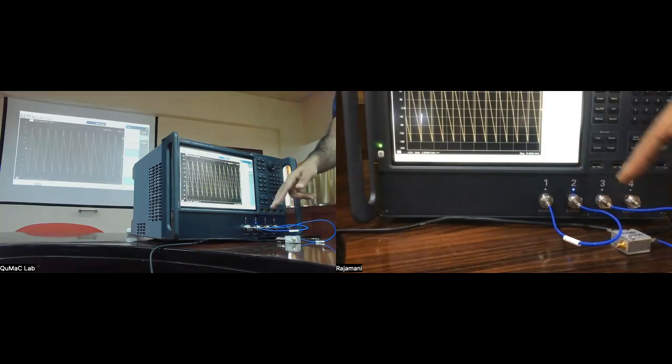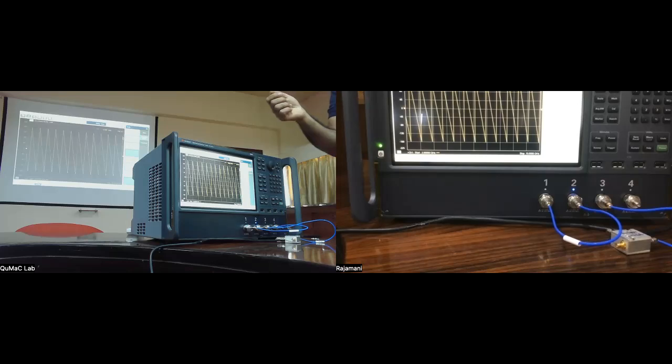This is a small cable, okay? In our experiments, these cables can be meters long, and for whatever reason, that's going to give me a huge amount of phase change over frequencies. I'm just trying to remove that trivial part. This is just a convenience factor. There's nothing wrong with what we saw earlier. You are removing the phase evolution, which is the trivial part, and cancelling it out. So if you overdo this, then you can cancel some of the phase evolution inside your system as well.